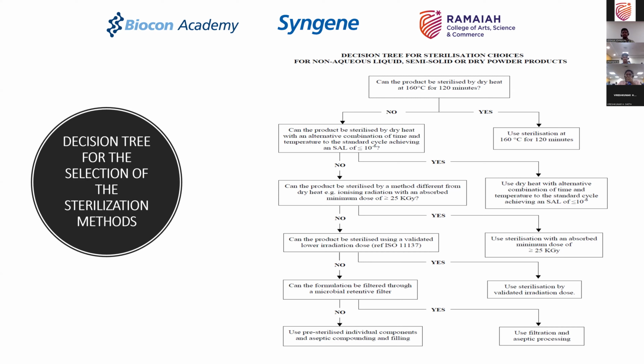By adapting automation, yes, you can reduce a lot of those errors, but you can't definitely avoid failures, because even in an automated process, if one temperature probe fails and it goes undetected, you could have a wrong temperature sensor giving you a wrong reading. Instead of 121, the temperature was actually 110, but it had a calibration error, or somebody forgot to calibrate it and it showed 120 degrees centigrade, and as a result you had a sterility failure.